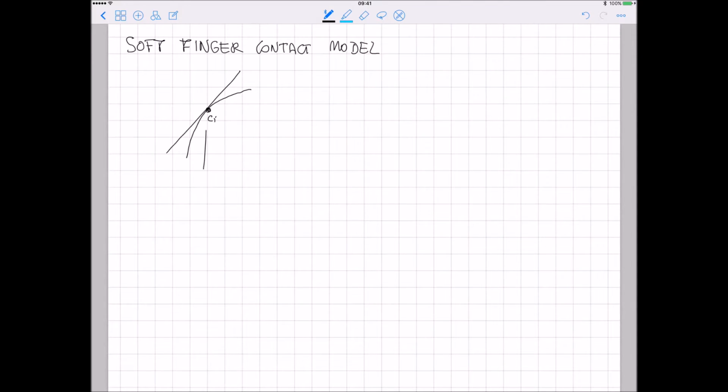So if I zoom in on this area, I see that the contact is not a point, but a small area. So what I have is not a contact force, but a pressure distribution whose resultant is no longer a single force, but also gives a torque component.